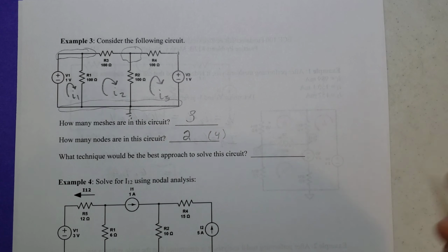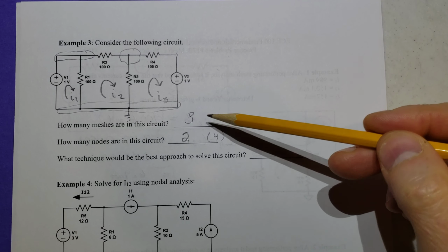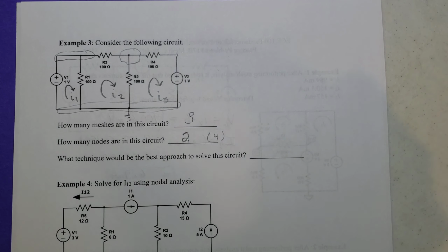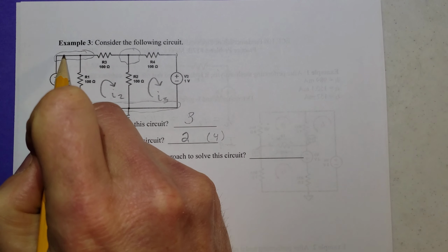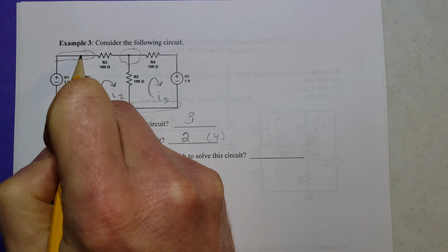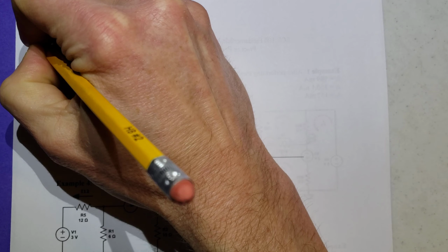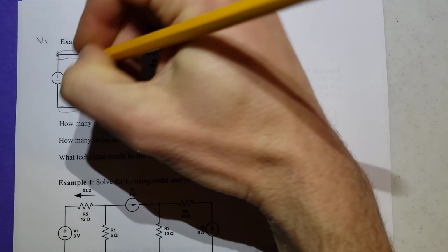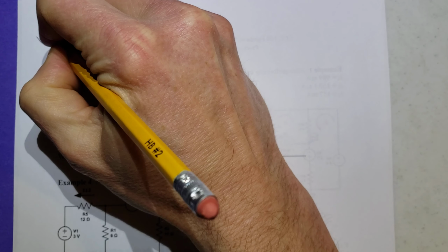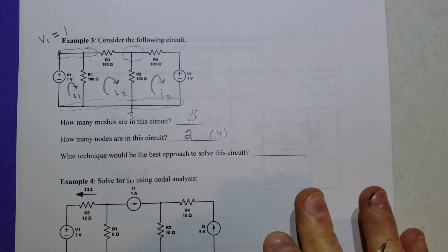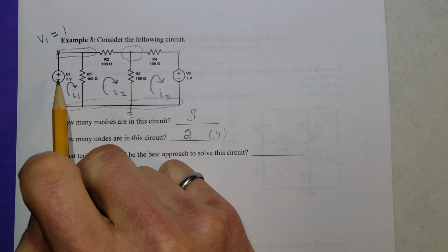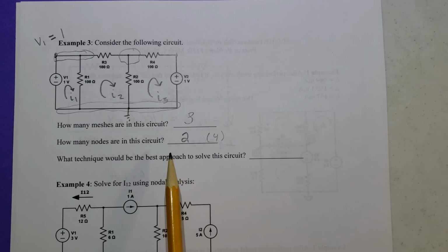So which would be the best? All right, well, the end of the story is 3 equations, 2 equations. Yeah, probably you'd rather choose the 2, but there's an added bonus for nodal analysis in this particular case, because if we look here and we say, okay, I'm going to write the equations for, wait a minute. If I choose this to be V1, I already know what my voltage is. V1 is going to be just 1 volt. So then, how many equations would I have?